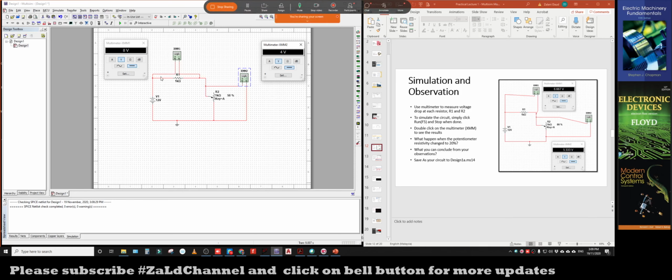All right. So why is this 8 volt? Why is this 4 volt? Because the value of this resistor is half. The value of this resistor is full, which is 1 kilo. This one is 0.5 kilo because it is 50%. If I make this 100%, meaning that this resistor is now 1 kilo as well.